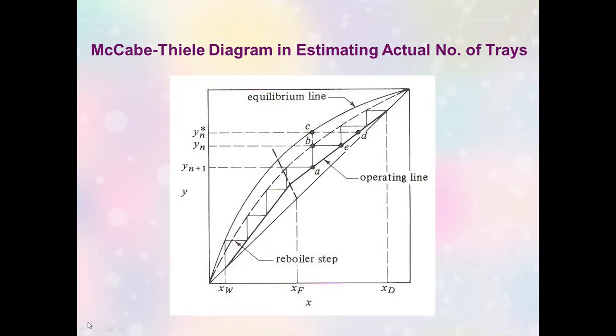Actually, the intersection of the equilibrium curve and the feed line is found through the intersection of the feed line and the enriching section operating line, because these three will meet at one point for the minimum reflux ratio, where we determine the pinch point coordinates. Did you get it? So, Doc, is the equation for the enriching section at the pinch point different?